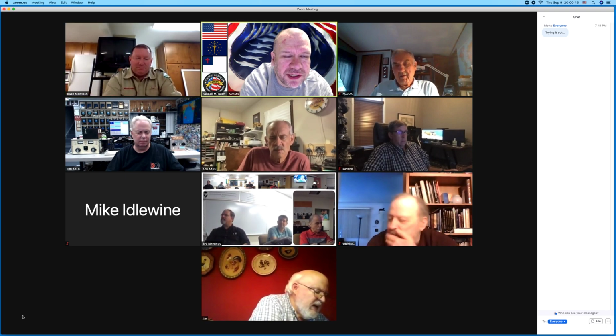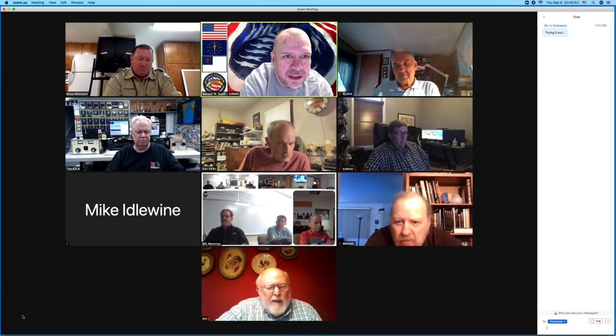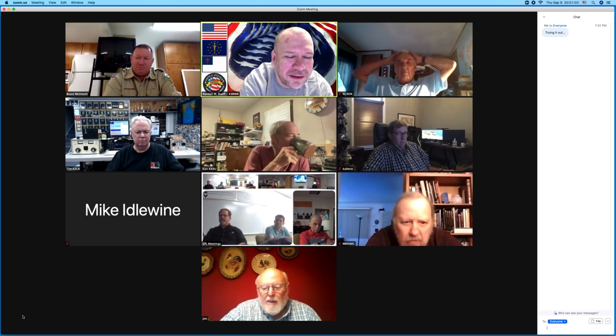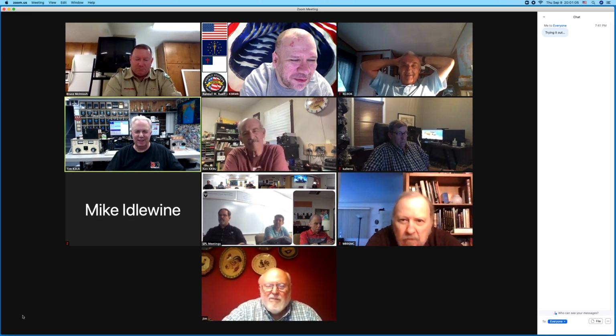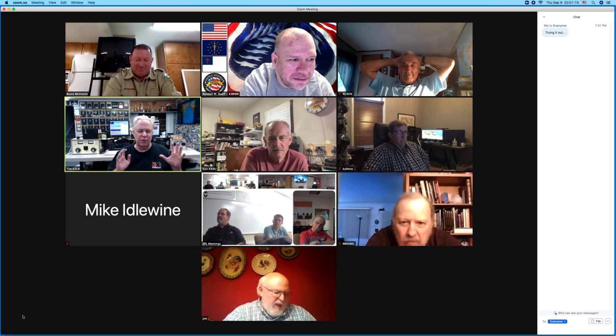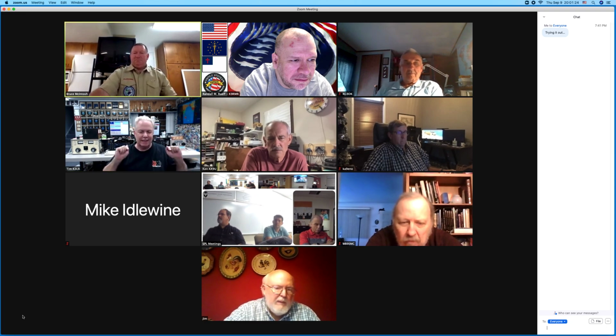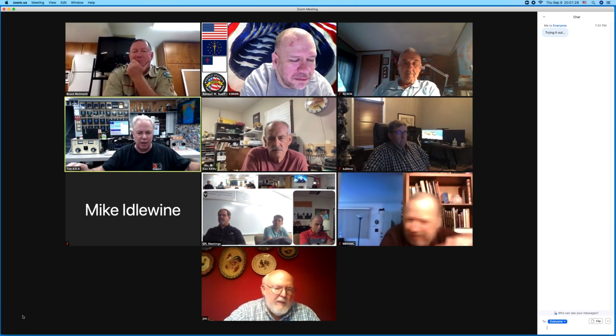I got one. I guess my question would be for a single radio. Obviously, you've got a lot more than one radio, but just for the single radio, as far as installation time and cost, on a minimalist budget, what can we get away with? There's no free lunch here. Well, I understand that. Here's the thing. Even with one radio, all just that slide that shows all the components of your radio station, whether radio, tuner, amplifier, coax switch, everything should have a ground connection to a single bonding bus, and then that should go off to the ground rod. Okay.